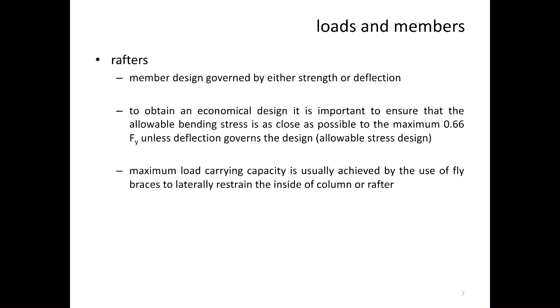So generally what we do, as I said before, is that our structures around the world are always over-designed. Even though you have a yield stress, and beyond the yield stress you've got the ultimate stress, which is the reserve strength, we still factor the yield stress. So when we check whether our structure can take the load, we don't actually stress it up to the yield.